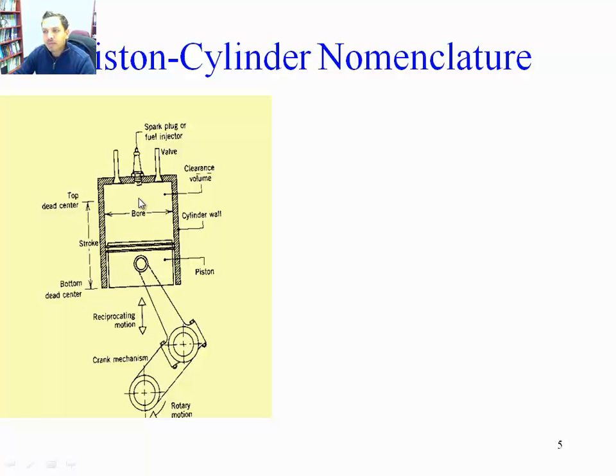There's a minimum of 2 valves in the cylinder, one exhaust and one intake valve. There's usually more than that in modern engines. There is a spark plug, the one that triggers the combustion in an Otto cycle, or basically an injector to inject the fuel in a diesel cycle.